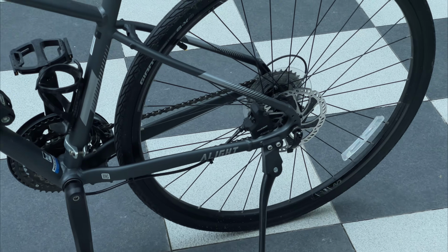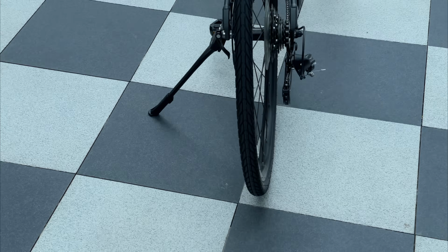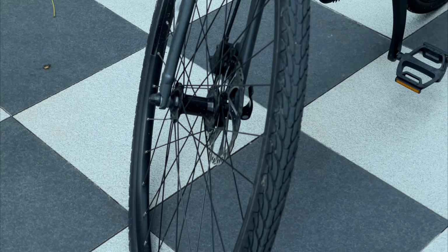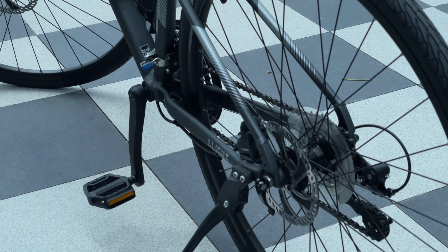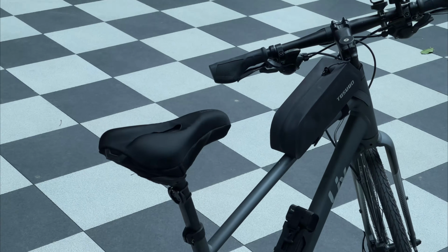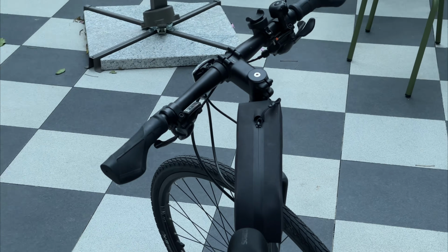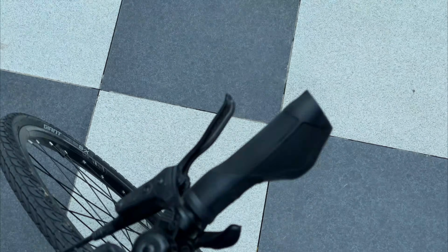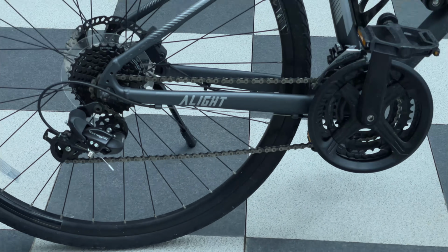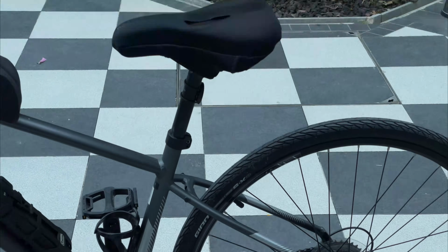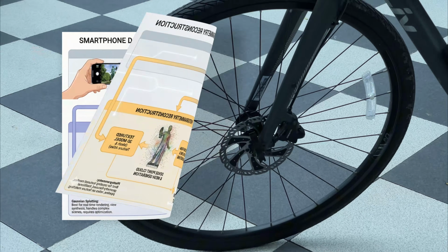When shooting, try to orbit from different angles, moving as slowly and smoothly as possible. You can orbit around a local part of the object. Not every photo needs to contain the whole object, but ensure that all parts of the object are captured. There is another good method. Imagine if the model were already generated, from which angles would you view this model? Then it is best to include similar angles when shooting.